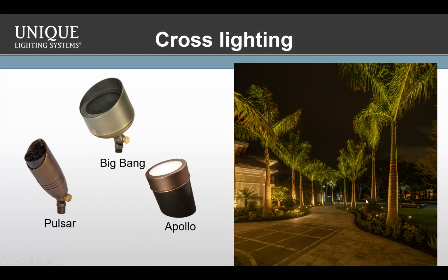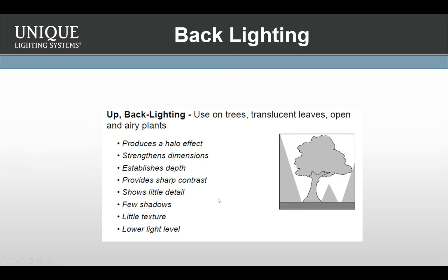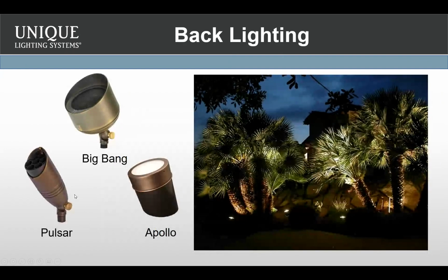I really push a minimum of two lights per tree, so you get this three-dimensional effect rather than spotlighting it. And this is a great point too: if I were to only light these trees on this side with one light all the way down, then walking back up the walk, the backsides of all these trees would be completely dark. The viewpoint walking up this way would be different than the experience walking down that way. So that's why I really like to push two lights per tree.